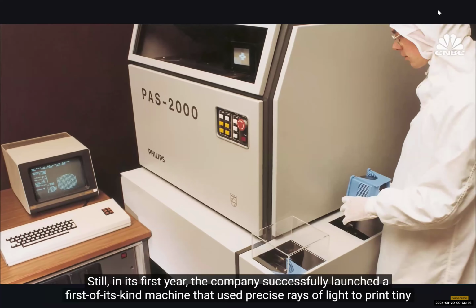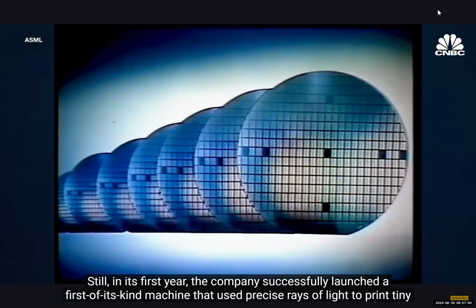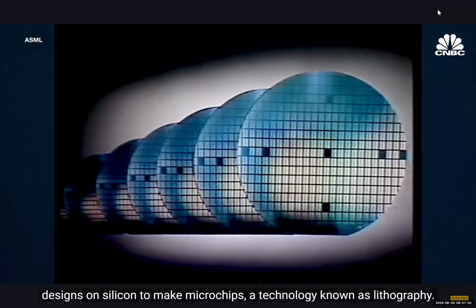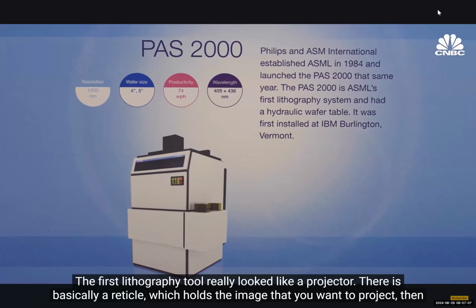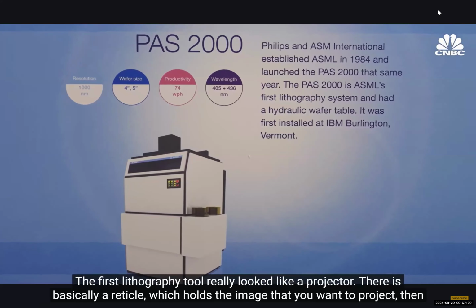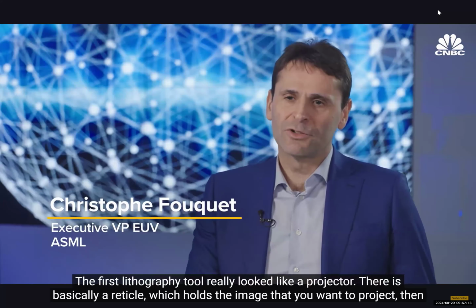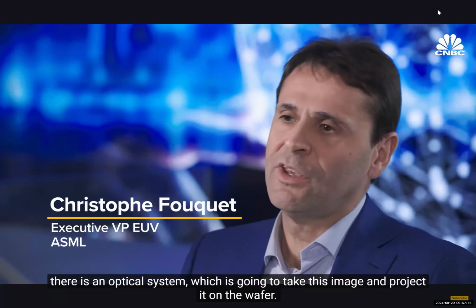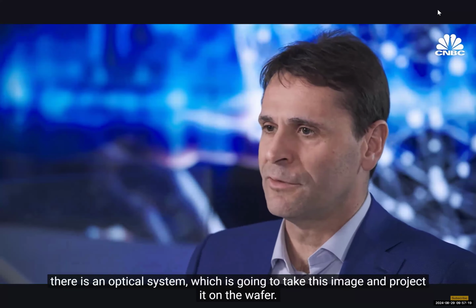Still, in its first year, the company successfully launched a first-of-its-kind machine that used precise rays of light to print tiny designs on silicon to make microchips, a technology known as lithography. The first lithography tool really looked like a projector. There is basically a reticle, which holds the image that you want to project. Then there is an optical system, which is going to take this image and project it on the wafer.